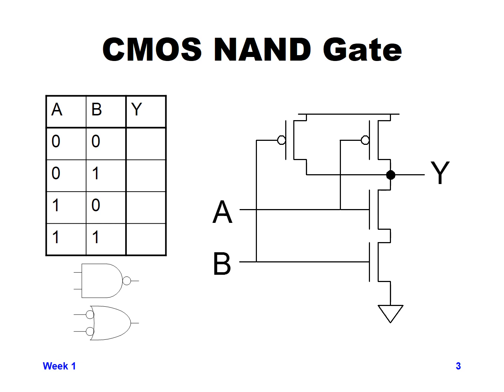And this is just showing, if you go back to logical functionality that you should have learned in other classes, there's something called De Morgan's rule, where you can take the output of a given type of gate and invert the output and invert both of the inputs and then convert an AND to an OR. So you can see in this case the output went from a bubble on the output to no bubble on the output.